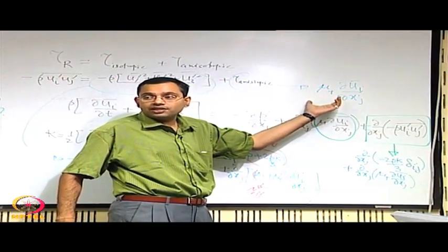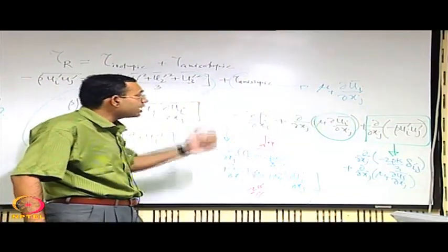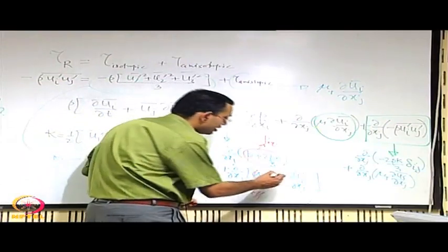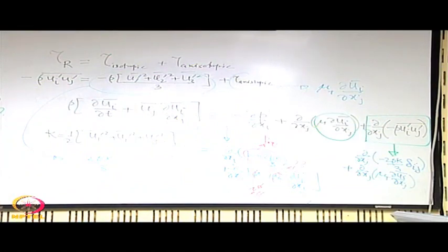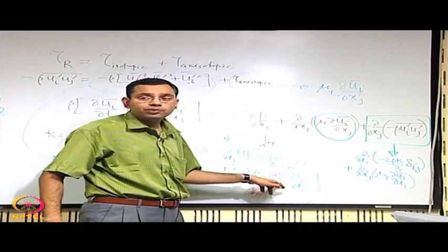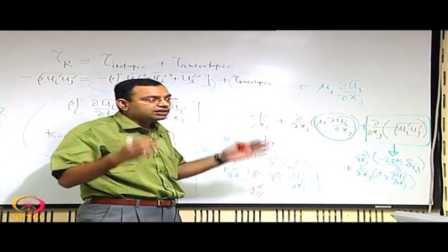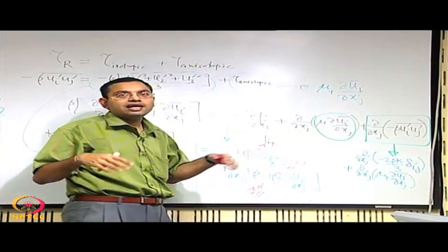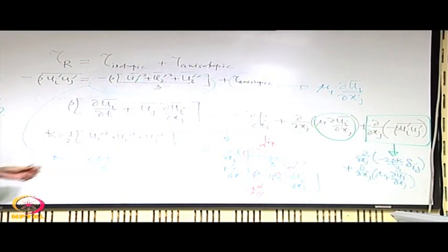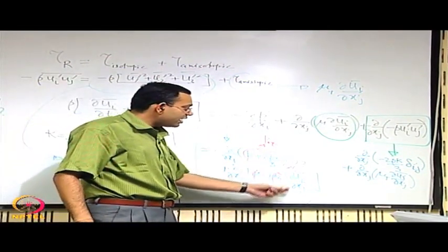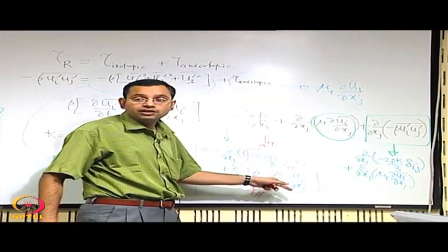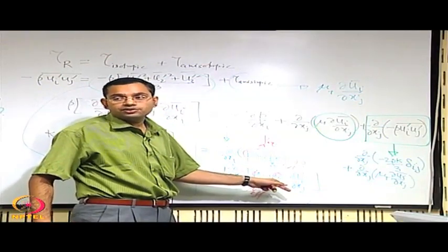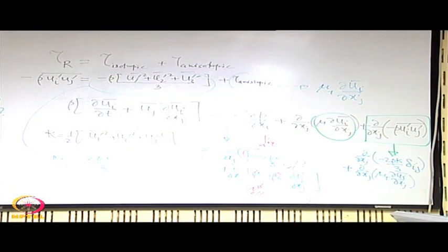We have seen that it satisfies the basic requirements of continuum mechanics, at least in form, but the big question is now that mu t is something which is not known. So, apparently it looks as closed, but it is not a closed system of equations, because you have a mu t which is not a fluid property, which depends on certain conditions in the flow in terms of the statistical averaging of the fluctuations, and therefore there must be an additional description or modeling of this mu t, which is one of the important jobs for turbulent flow modeling.